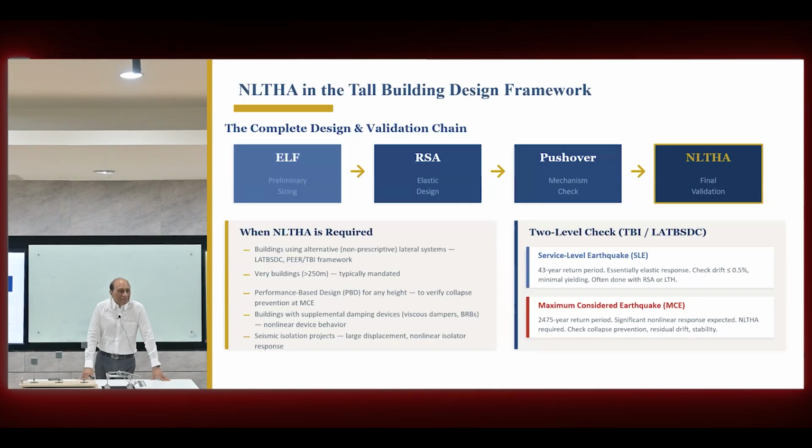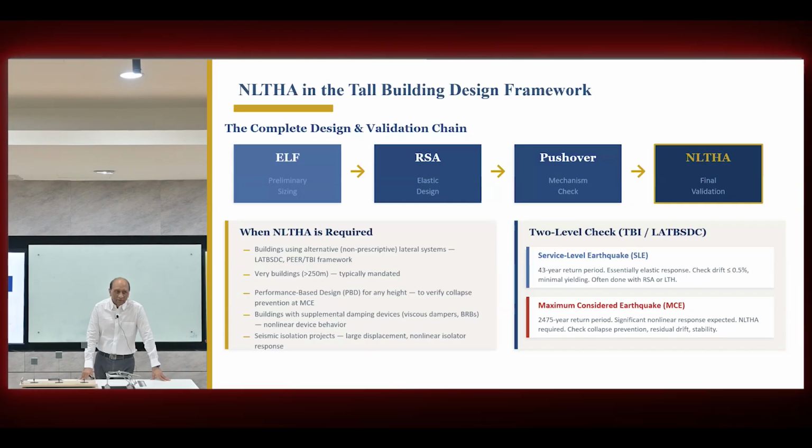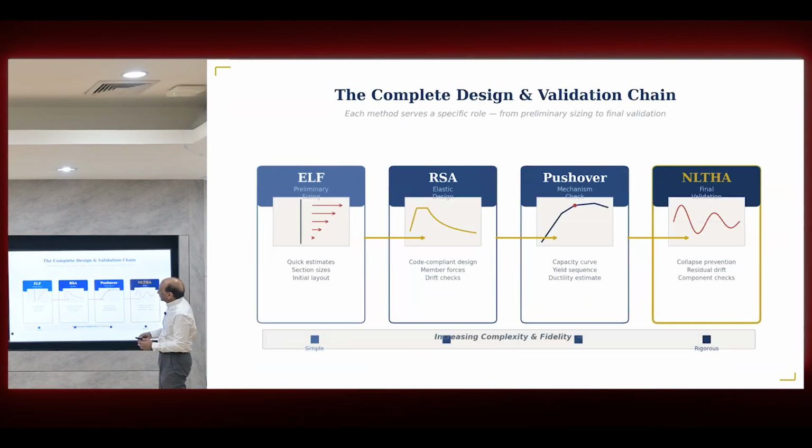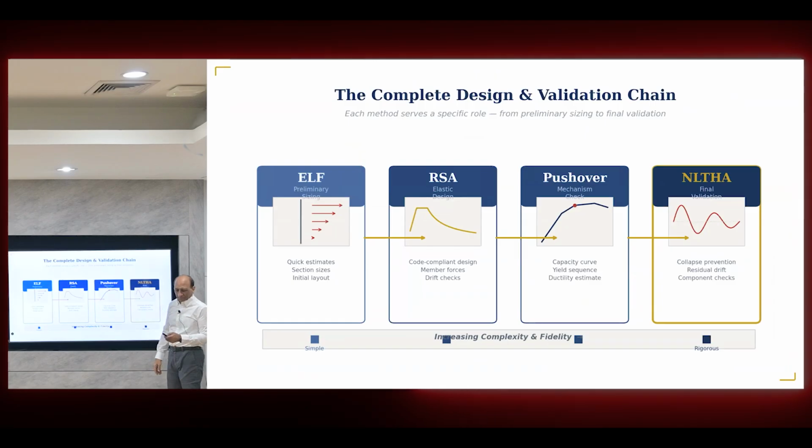Because every other method cannot answer this because it's based on assumptions, unrealistic, most of them. So if somebody really wants to know the answer, is my structure safe for this particular earthquake or this location or this one, then you need to go there. So that's the quick one, preliminary sizing, response spectrum, push over, nonlinear time history, visually showing you how this happens.